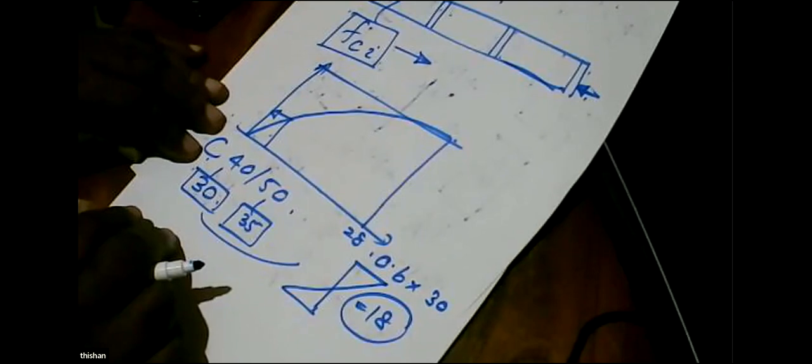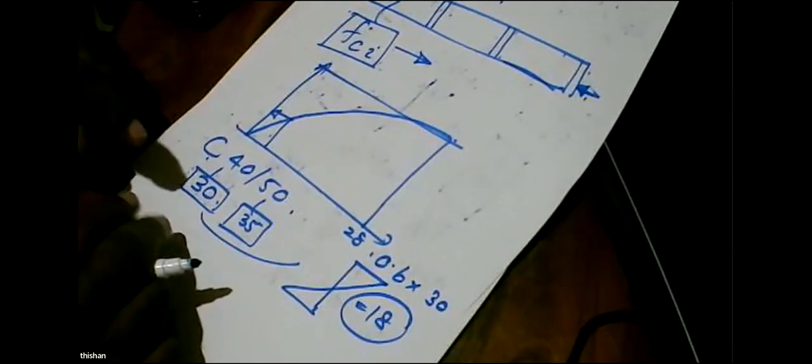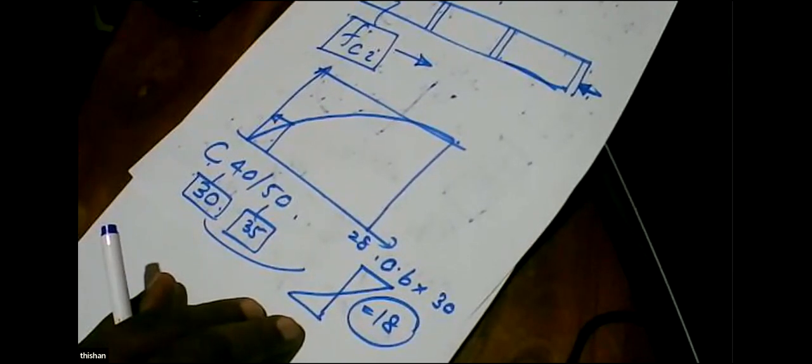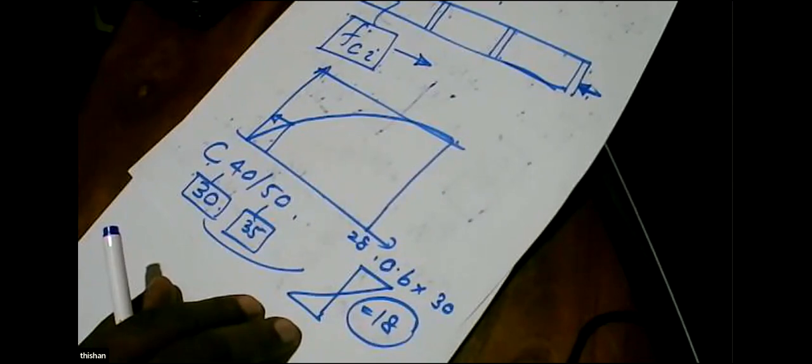Because if we are to reach the maximum strength or the specified strength, we have to stop manufacturing of beams and wait until concrete gains the adequate strength. It's difficult for us to do that in a profitable way, so what we do is we specify a lower strength and say you can stress it at an early stage of strength development. So after about 7 days of casting the beams, you will find it has reached 30 megapascal, or after 4 days of casting the beam, you will find the cylinder strength is 30.